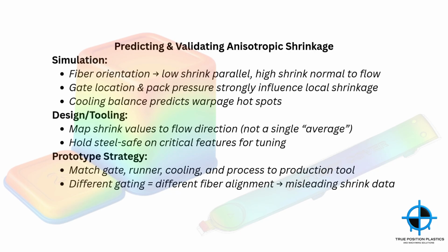And it's fascinating because the fiber alignment isn't uniform through the part's thickness. Near the mold walls, you get high shear and fibers aligned with flow, but deeper inside, the flow is different, and fibers can orient differently, sometimes even perpendicular in certain layers. It's that complex layered structure that simulation helps predict. Okay, so simulation is key. What else? Tool makers also directly adjust the mold dimensions. They build the mold cavity slightly differently, applying different shrinkage compensation factors for dimensions parallel versus perpendicular to the expected flow direction.